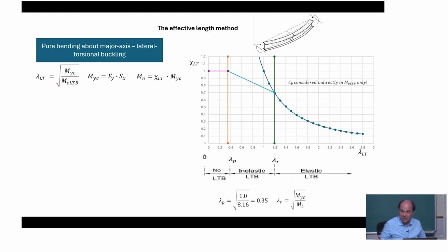But if you don't know what your arm brace length is, simply because you cannot find fork supports, then there is no arm brace length. Or you have fork support, but you have a trapezoid sheeting on top of it. Then what is your arm brace length? Still the one without the trapezoid sheeting?